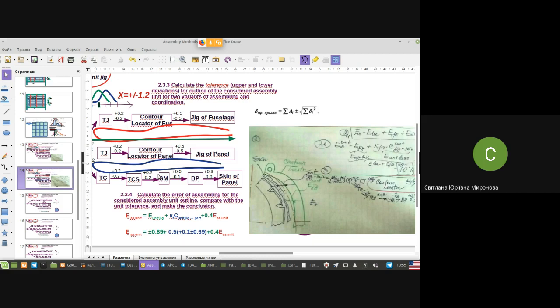And in case of casting, you can't penetrate inside of the casted form or casting form or forging die, for instance. You can't penetrate inside. You may make a part either equal to the forging die or less than the forging die, but not more, certainly. And when you are working with a cutting instrument, you may make errors as a greater object or as a less object than necessary, because you use a cutting tool.